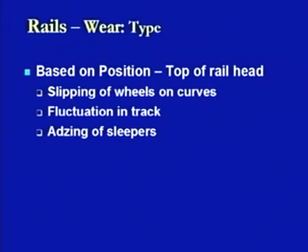We have seen in the case of the coning of wheels that if we are not providing the edging of the sleepers, that means we are not providing the seat in which the rail section can be set in at an angle of 1 in 20, then there will be concentration of the loads at the tops of the surface, where there is a point of contact between the wheel and the rail section. Due to this, there will be a sort of striking behavior, an indentation behavior, at that point of contact. So, the wear will start taking place from that location.